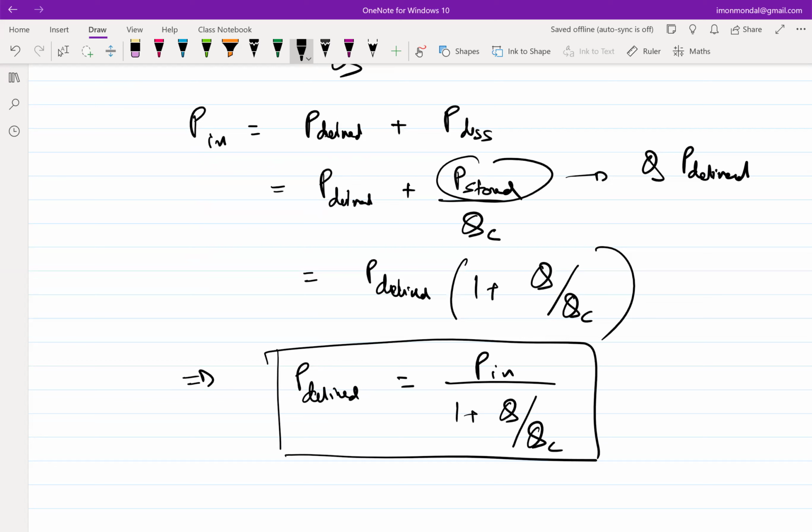It is basically telling you that Q is essentially the network Q, again, QC you cannot do anything about. It comes with the network, with your matching network component that you have chosen. Q also probably you cannot do much because omega is fixed. Resonant frequency ensures that the value of the component is also fixed, right?